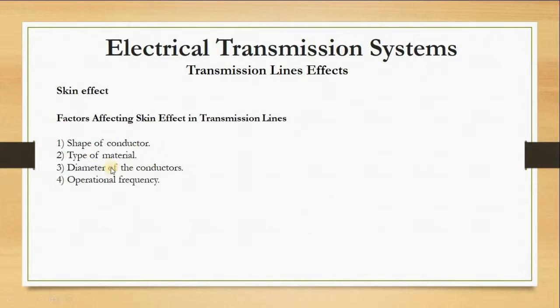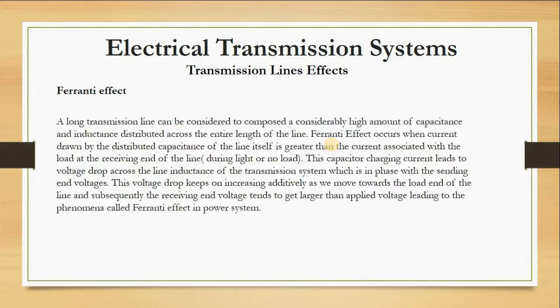So these are the factors that affect skin effect: the shape of the conductor, the material, the diameter, and the frequency at which it's operating. These are the factors that determine the severity of the skin effect. Then we also have the Ferranti effect.